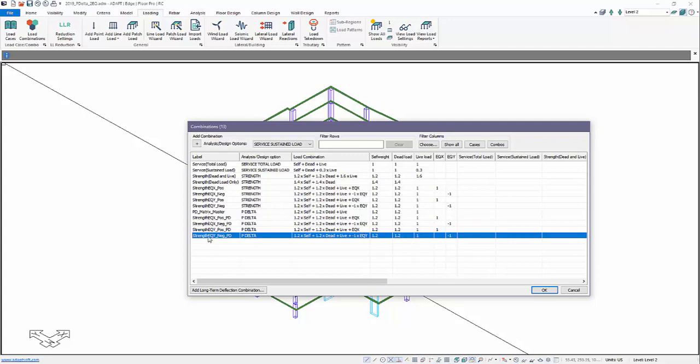The geometric matrix is then used in combination with the general matrix for the structure, and we produce a solution for each subsequent combination based on this first initial P-delta combination without the EQX. Now, if we wanted to produce individualized combinations, then we would actually remove this.